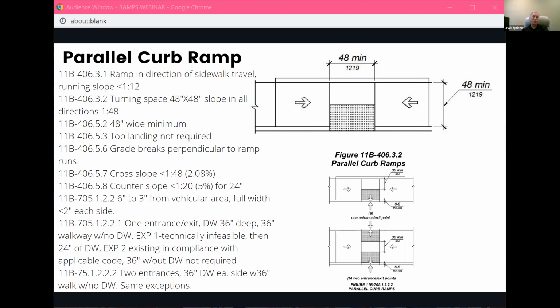One of the things I see a lot too is on ramps, where the code shows 5 foot by 5 foot landings. Then I'll go out and survey, or I'll review drawings, and the 5 foot by 5 foot landing is shown, but then they inset railings inside of that, and all of a sudden you're at 4'2" by 4'2" inside clear, which doesn't actually meet the code. Does that make sense? So you have to look at multiple sections of the code sometimes in order to make sure you meet all code sections. Got it. Thank you. You're welcome.